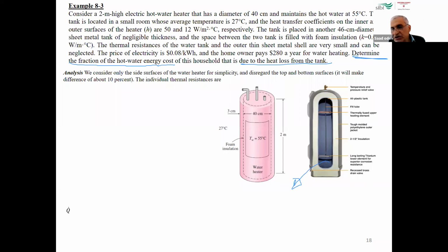Insulation will not stop heat transfer, but insulation will minimize heat transfer to the lowest level. But we need to know how much we are losing with the insulation. If you know the energy lost, we multiply it by the cost of the energy, which is here 8 cents per kilowatt hour,